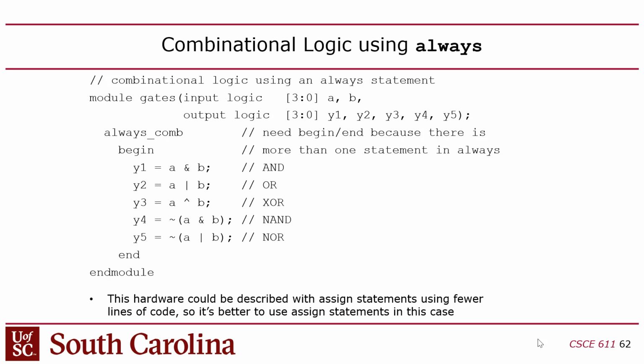Does that make sense? Is there additional overhead in synthesis when you use the always instead of just assign? No, they're equivalent. So if you use an assign or an always to do a mux, they'll be equivalent.